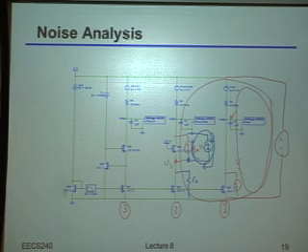Now, that's really good news from a noise standpoint, because notice, as long as the current is flowing through this internal loop, it has no effect whatsoever on the output voltage, right? Because you change this Vs relative to ground, but if I'm measuring this output voltage relative to ground, who cares? It didn't do anything. Okay? So as long as you get this noise current to circulate internally here, that cascode should not be adding very much noise at all.